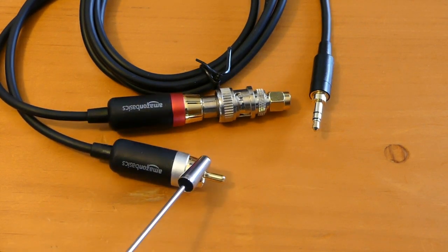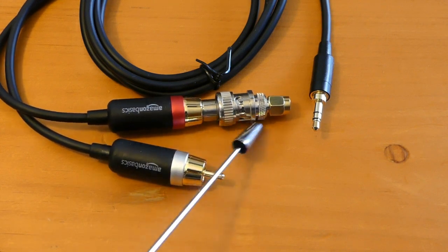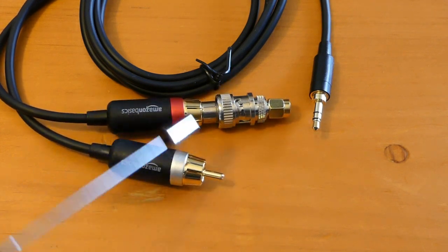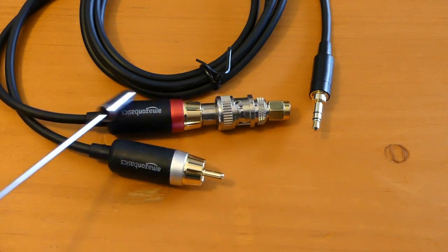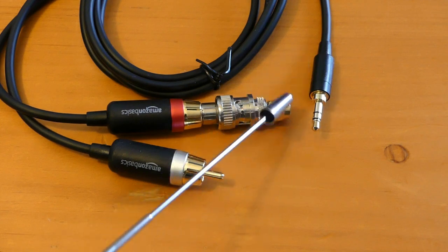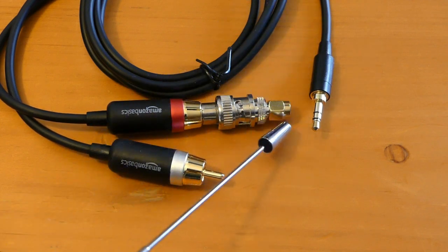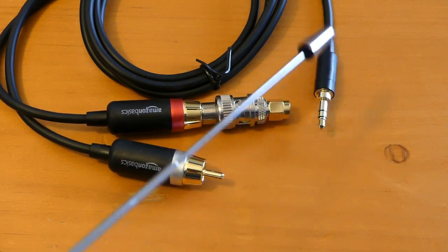You can use either channel, left or right, it doesn't really matter, so we're just picking one channel. We're not using any kind of IQ, so we don't need left, right, any of that nonsense. It's just one audio file. We're simply going to take the output of this, put it to the I port of the mixer, and shift this spectrum up to 7200 kilohertz.